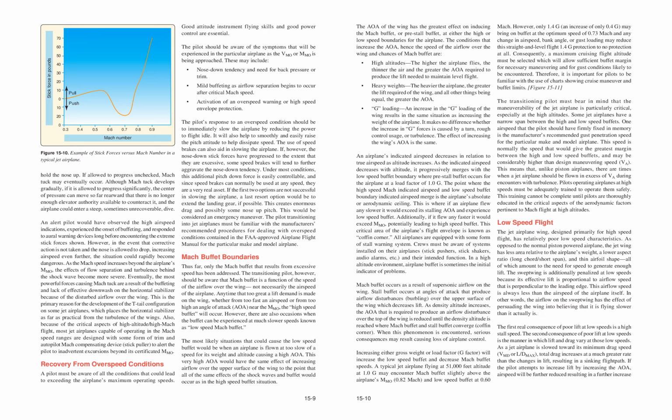Mach buffet boundaries. Thus far, only the Mach buffet that results from excessive speed has been addressed. The transitioning pilot, however, should be aware that Mach buffet is a function of the speed of the airflow over the wing, not necessarily the airspeed of the airplane. Anytime that too great a lift demand is made on the wing, whether from too fast an airspeed or from too high an angle of attack, AOA, near the MMO, the high-speed buffet will occur.